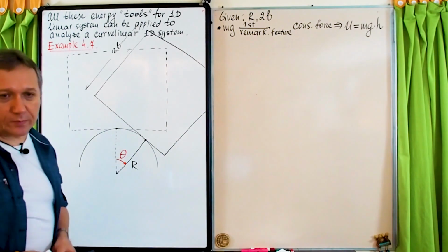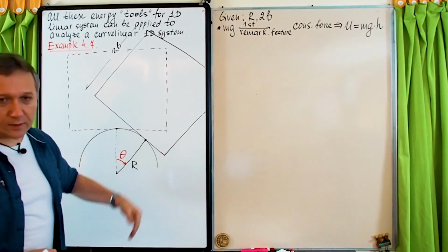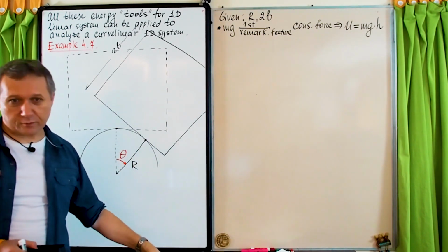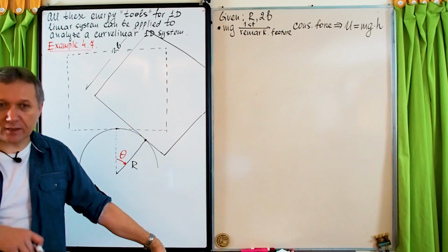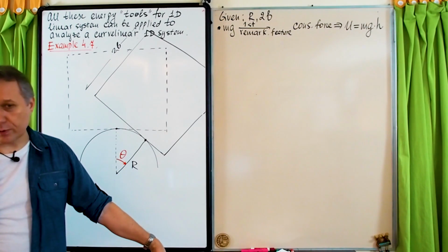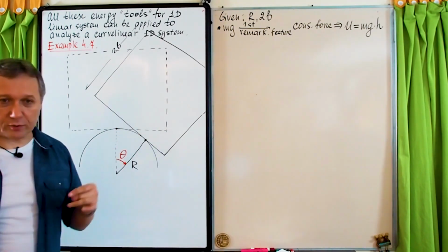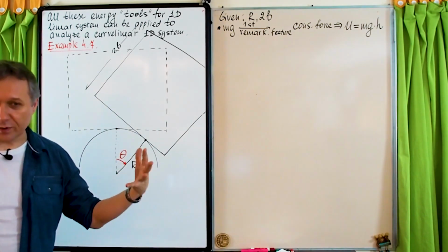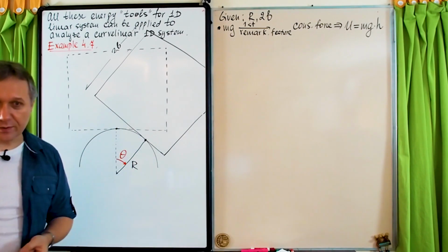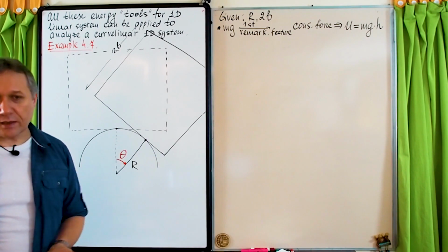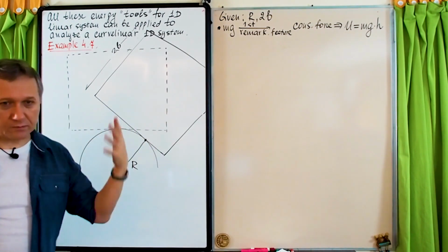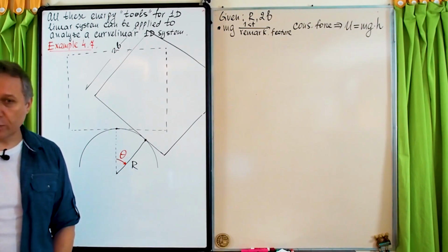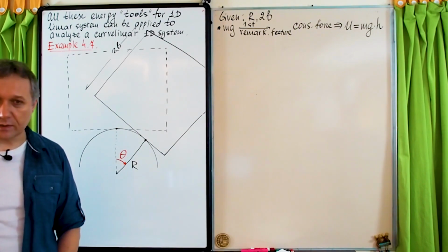Then, second, of course, there must be plenty of friction force on the cylinder so that this cube can rock from side to side. And of course, you know which friction force we have here. You remember we have static friction force, kinetic. Here we have static friction force because there is no sliding. So the point of contact at any moment of time is stationary. So since there is no displacement, work done by the friction force, in this case static friction force, is zero. So static friction force in this case doesn't play the energy game. We're planning to use the energy approach, but friction force in this case doesn't care about our energy game. What it does is just act as a force of constraints. And we're going to use the constraints at some point.